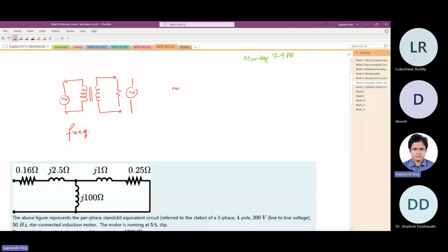If you simply take this circuit, say one AC voltage source feeding to another AC voltage source, which is our typical power system circuits, or maybe an inverter feeding the grid, whatever, E1, E2. The condition for non-zero average power flow is that frequencies must be the same. Otherwise, there will be pulsating power flowing, but you will not get any non-zero average power.